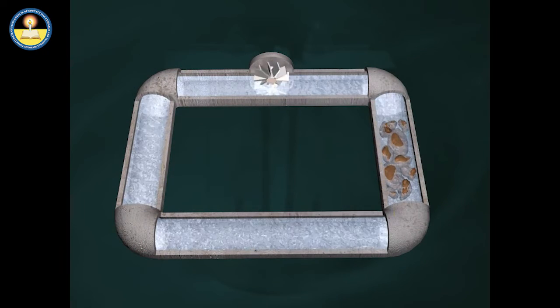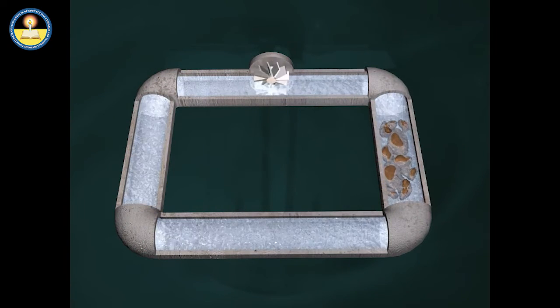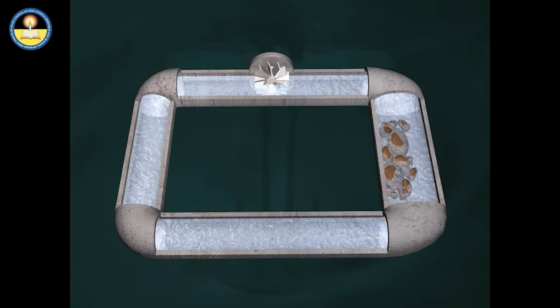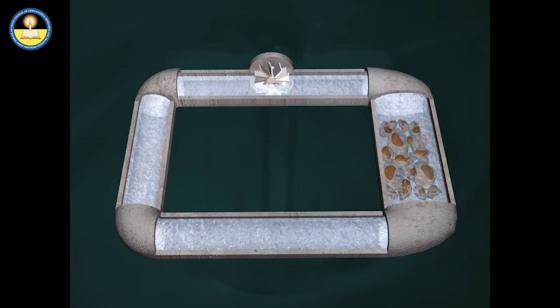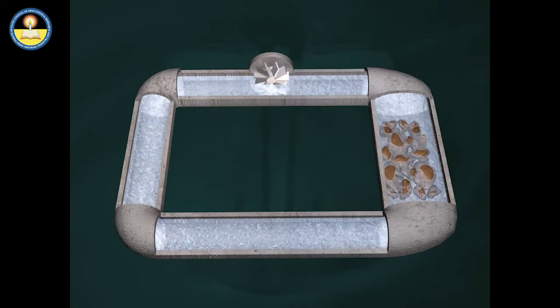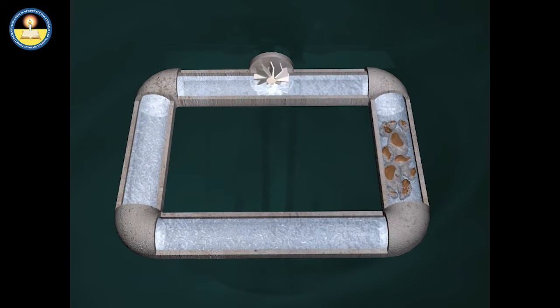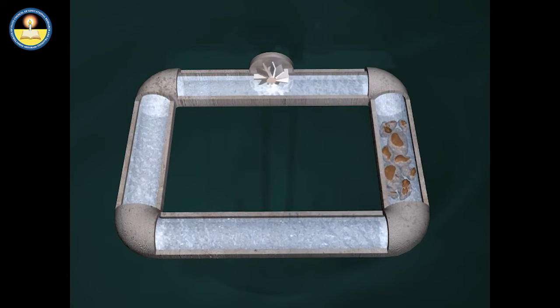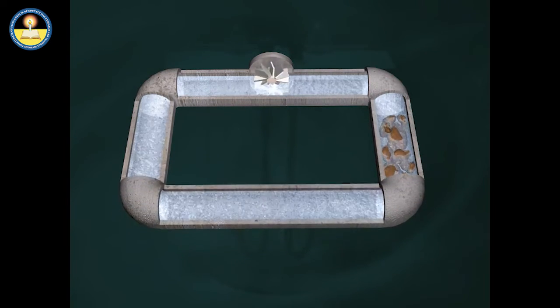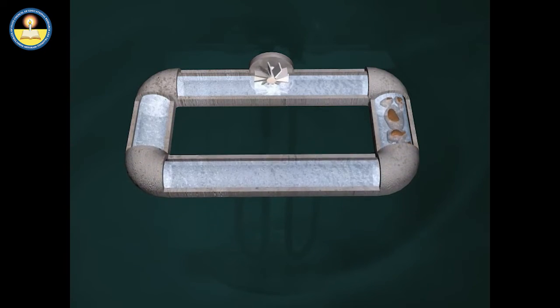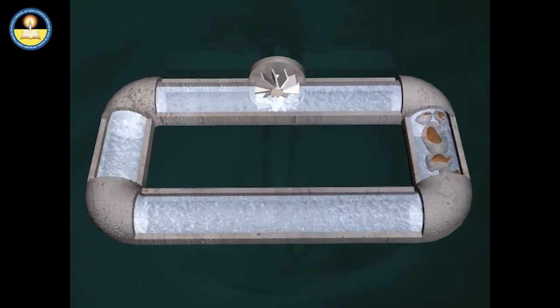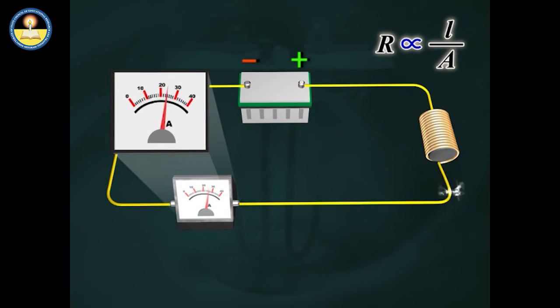Bimetallic strips are commonly used as an automatic switch in electrical heating devices, such as electric iron, electric kettle, etc. A bimetallic strip consists of two strips of different materials, such as brass and iron, but of equal length, placed back to back so that they cannot move separately and riveted together at different points along their lengths, such that they cannot slip sideways.